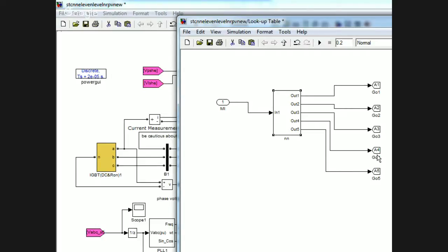So real time also you can implement it. For that only this is required. You will just be removing these blocks and this block and you will connect the real time. But in real time, one thing you have to remember is scaling of data. Say you have a 230 volts supply or you have 415 volts. You can't give it to your DSpace directly. So what should be done there?